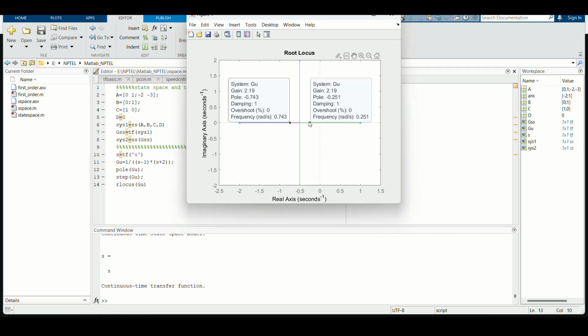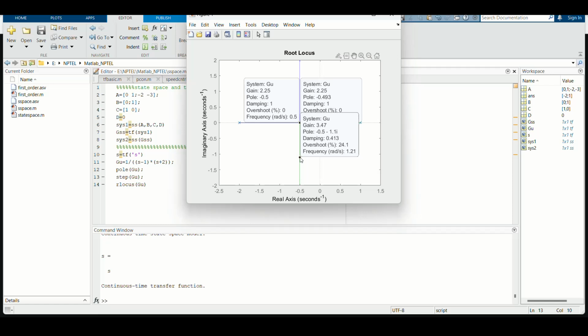As we increase gain k, we get critically damped response and both poles shift to this value, because here we have a breakaway point, so both poles are the same. At a gain of 2.25 we have equal poles at around -0.5, and as we increase the gain k more, we will get complex conjugate poles. So let's say we want both poles real and on the LHP.